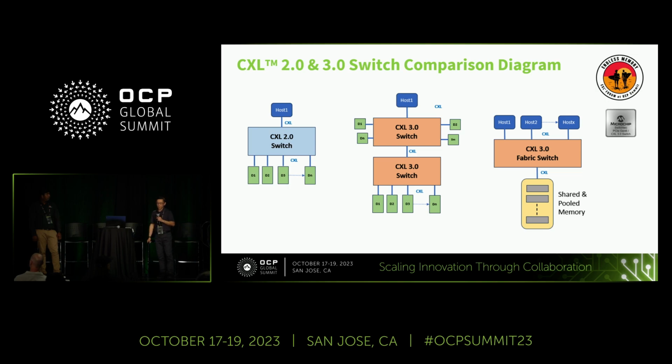And here's a typical comparison between the CXL 2.0 switch and 3.0. With 2.0, you can see that it's a single layer switching. You connect from host to endpoint. Very simple. You cannot do a whole lot through a switch. But once CXL 3.0 is out, then you can actually cascade multiple switches and do highly complex fabric interconnections based on how you want to interconnect your host to multi-host applications. And looking at the fabrics of CXL 3.0, we can see that the key advantage is it allows customers to configure how complex they want it to be. So the interconnection is up to the end user's imagination. So it's a flexible switch that we're going to be providing.